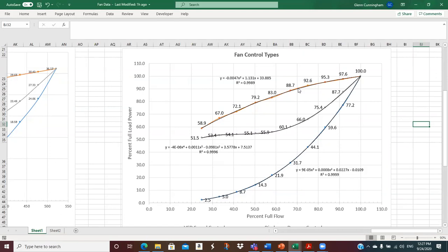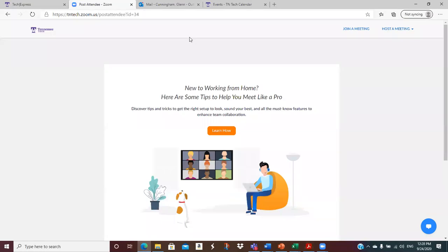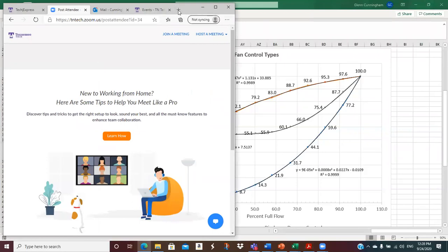Okay, and then you have a measured case for here, and you can come down and pull a number off this and use that to estimate what the power would fall to if you put a VFD on there. And I told you to add a little 3% extra for drive losses, even though I think these numbers have drive losses in there, but you'd rather be a little conservative. So that's one way to do it. The other way, you could go play around with this ABB. I haven't done this in a while.